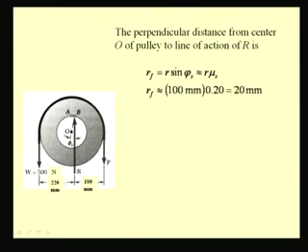So, we find the radius of friction as R sin phi s, because here it is an impending slippage case, and so we take the coefficient of static friction. So, the radius of the circle of friction will be R sin phi s for small angle, which is equal to R tan phi s or R mu s.